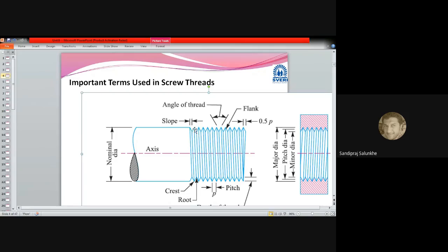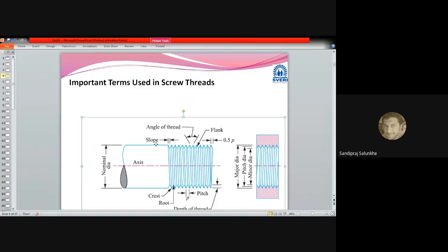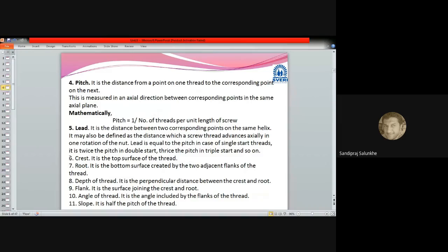This lead is also termed a lead because of how many rotations are required to move from one point to the similar point on the threads. In some threads it may be achieved in half a rotation, in some threads in two rotations. That will differ for each particular screw. That is also known as starts, single start screw or double start screw, for threads.